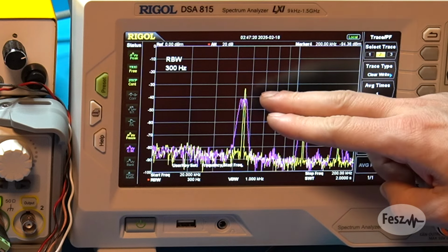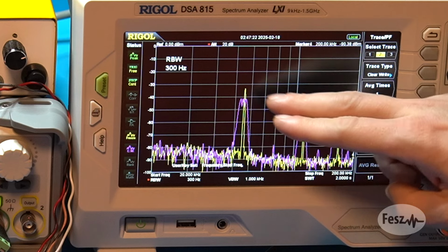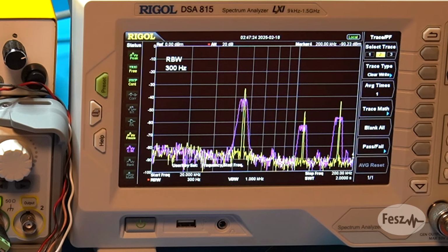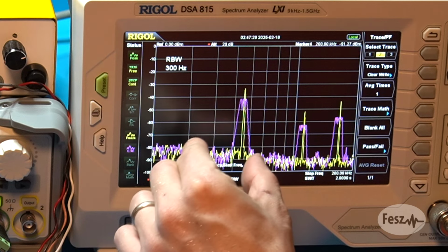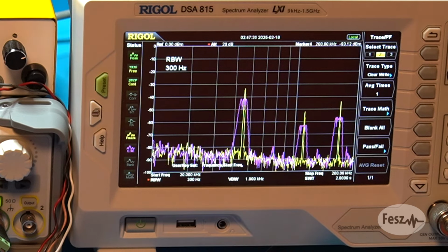However, the useful phenomenon that is occurring is that the oscillating frequency is now variable. So we can see that it has spread out a bit, and thus the perceived emission levels are lower. So the same noise energy is being emitted, that did not change. However, since it's not a single frequency anymore, the peak noise value does seem lower.